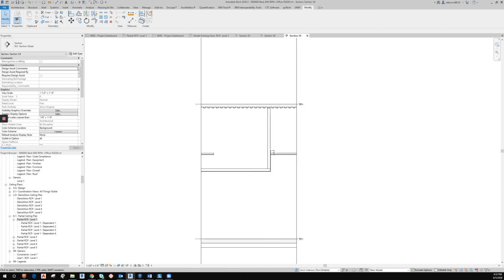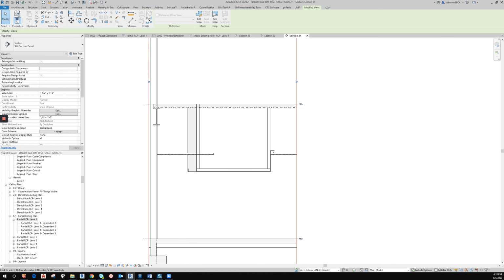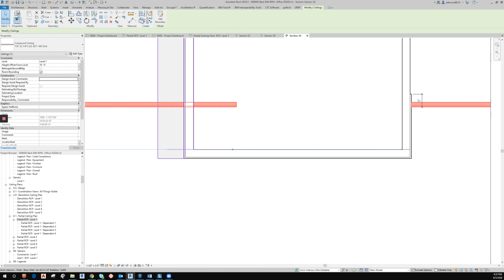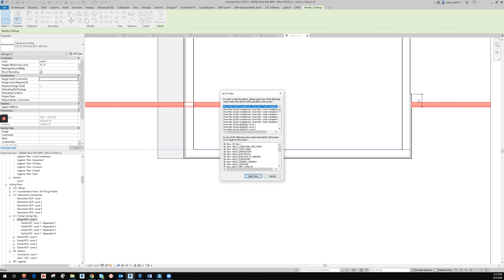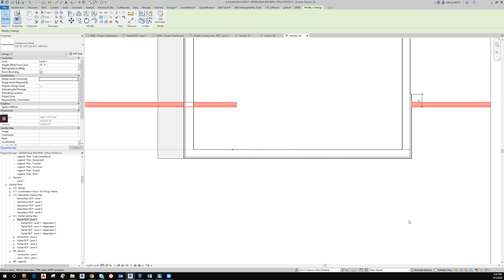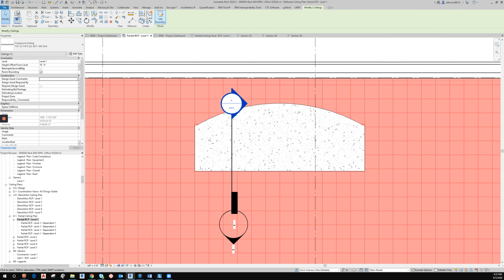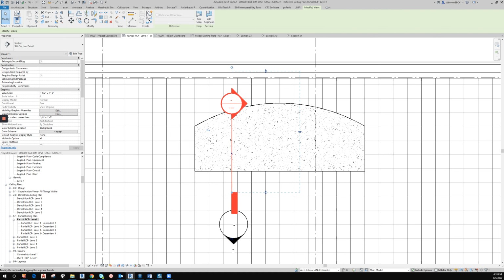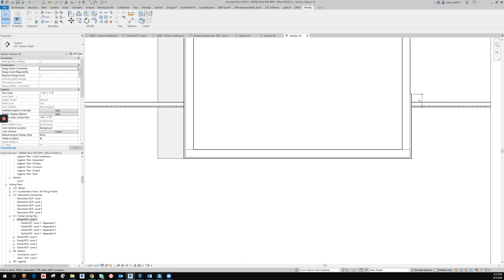And I've got this lovely arched wall that has the same cleanliness. And we can come back and edit our boundary for our ACT ceiling as well. And again, on that one, you would want to use pick wall, but not extend into core. And now you have a beautiful dropped soffit over your nurse's station or whatever the case may be.